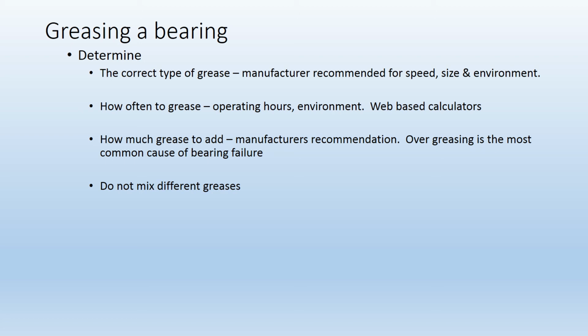And how much grease do you need to add? Again, you don't want to put in too much, and you also don't want to put in not quite enough. So you want to get that Goldilocks amount. If the manufacturer gives a recommendation, follow it. And lastly, don't mix up different greases.